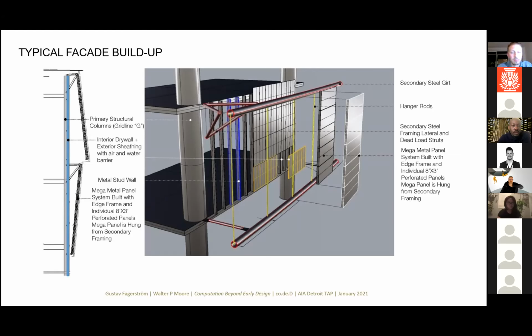So our system comes into play at that interface, where these struts, if you see the double triangle here, create a moment connection, so that this top horizontal tube, which was known as the hoop, becomes a moment stiff gravity connection. So that's where all the self weight of the whole system is taken up and goes back via these struts into the primary system.